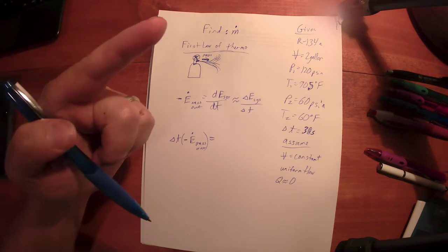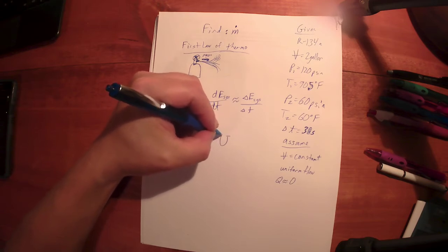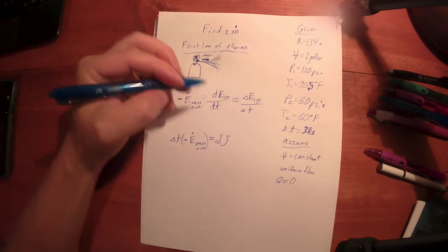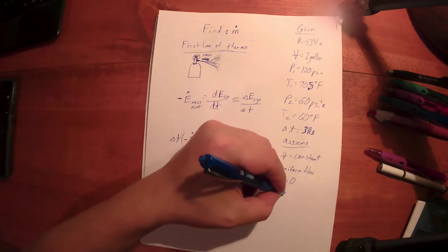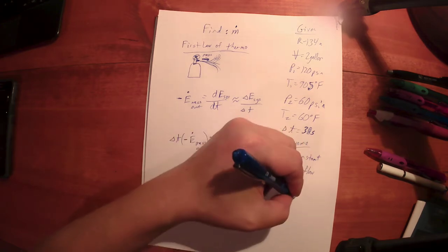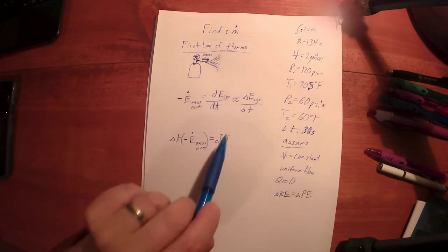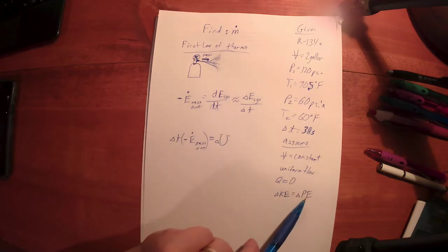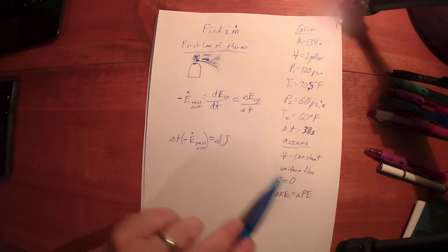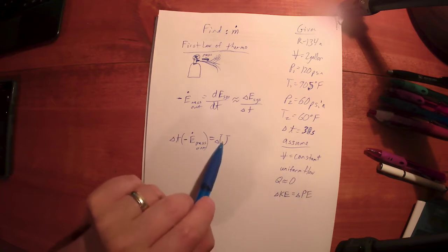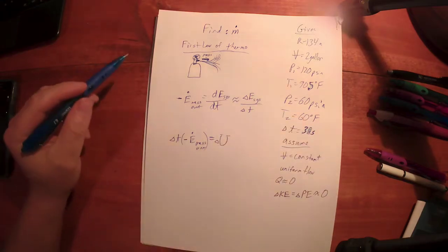Okay, you got it? Right, so the three types of energy that can change could be internal, right? Change in internal energy. It could also have a change in kinetic and a change in potential energy. We don't have any information about a change in velocity or a change in elevation. We know it gets dropped. We don't know how much, and compared to delta U, the change in potential energy is probably millijoules, and this is probably kilojoules. Or in this case, fractions of a BTU, and these are BTUs. So I think we're safe to assume those are negligible.